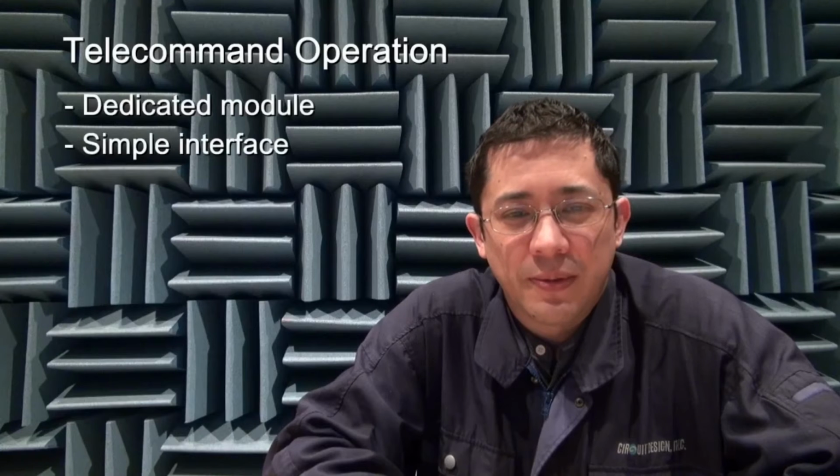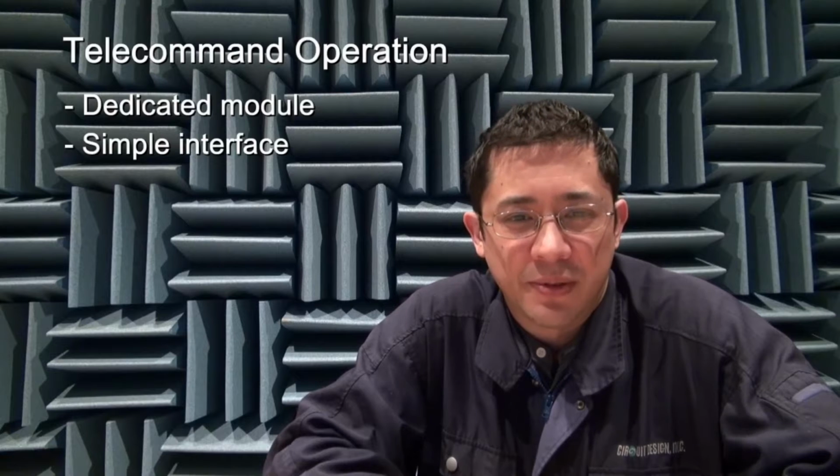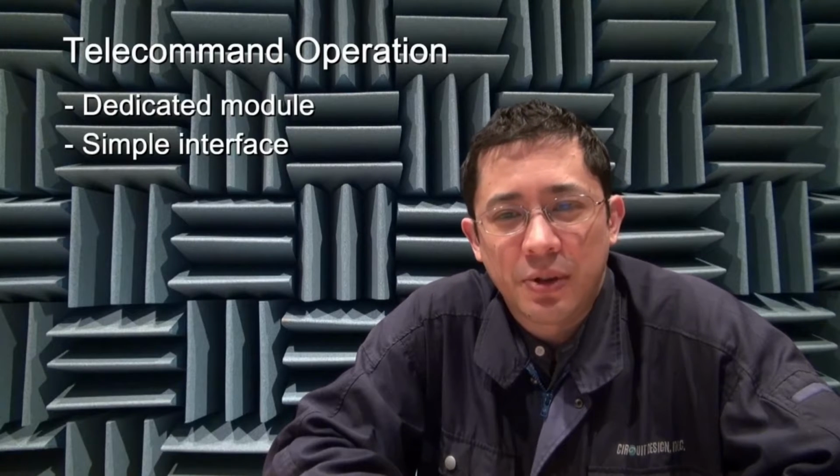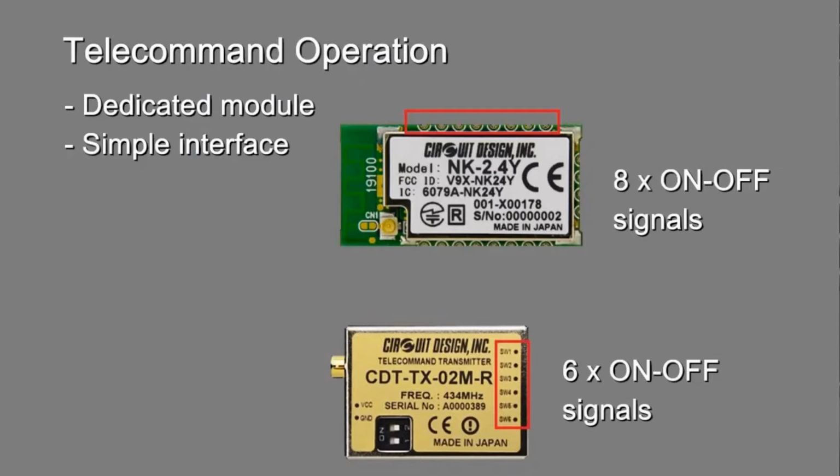The NK2.4Y and CT modules have direct connection for input and output signals. You can see that one module can process up to several switching signals: 6 signals for the CT and 8 for the NK2.4Y. Therefore, the engineer does not need to spend any time to develop a complex interface to use the modules.